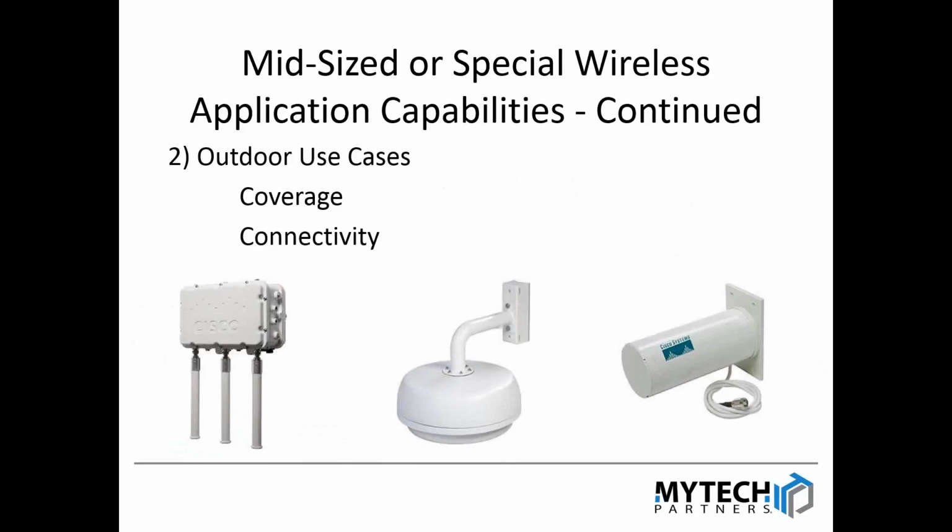The negative is, and I think of two scenarios that I've heard of from customers over the years, that if this is across a street, for example, and a big semi-truck happens to be stopped at the stoplight directly in the line of sight of your wireless signal, it might interfere with your connectivity. So that could be an intermittent problem if your line of sight isn't high enough. It's kind of funny that could happen, but it's something to be aware of: what might get in the way.